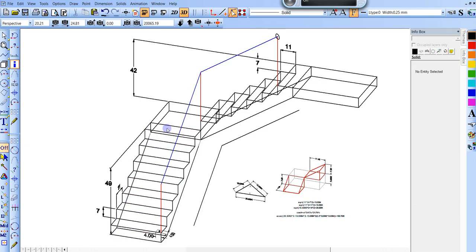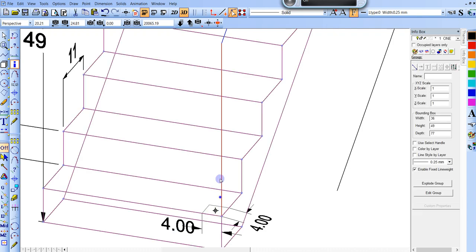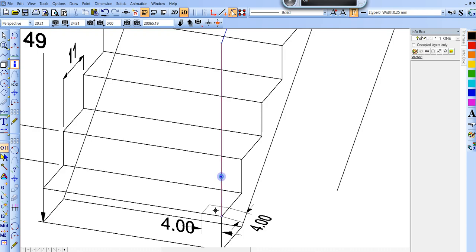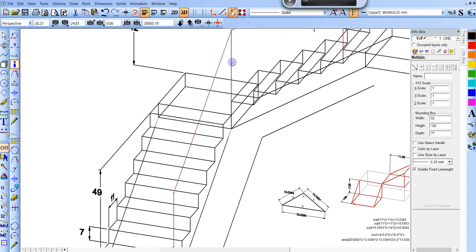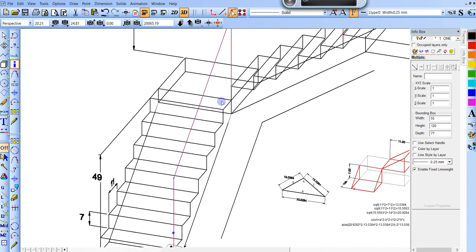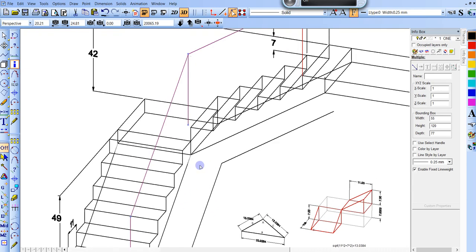So what you need to do is design the stairs before you get to the handrail. If you don't, you're going to have problems, and I'll show you why. So typically your handrails are not going to be on the theoretical corner, right? So if I take this piece, take this handrail, take this stanchion, Control H. I'm going to move it over to the center of that plate. So let's say it's a 4x4 plate or something, because that's the dimension. So it's 2 inches from each corner. Then I'm going to lengthen that.